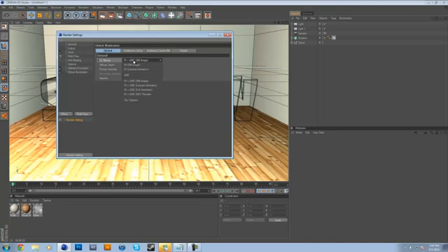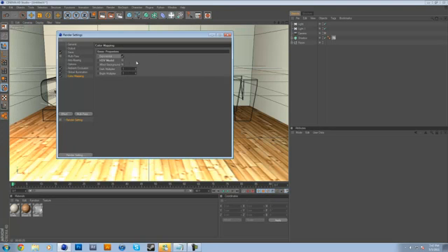If I was to leave it as the standard, as just IR, you won't really get shadows. It'll wash out the shadows, but we don't want that. And I'll pop that diffuse depth to about 2. And irradiance cache, we can keep that at medium. And medium, we don't really need high because there's not that much going on. And then last but not least, we'll come to color mapping. And I'm just going to turn off HSV model, just keep it as exponential. So that is about it.